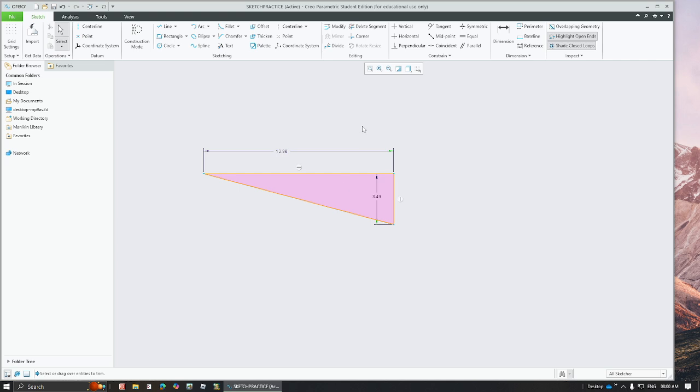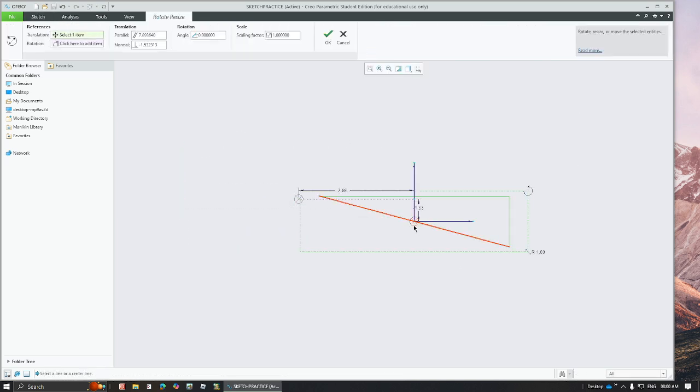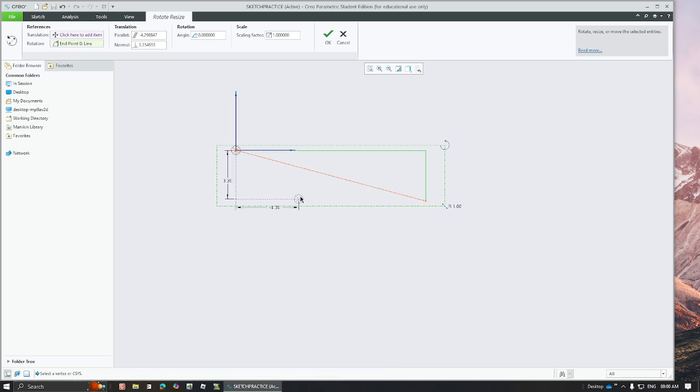All right, you also have the option to select the entities and click on this button, which allows you to move the entity to wherever you want. You can also right click and move this reference point to some selected reference point, and then left click to move it wherever you want. It will also show a relative position from the initial point so that you can move it with an exact value. This value here shows us the scaling factor, which you can double click and change.